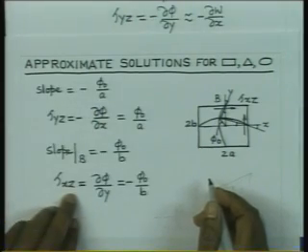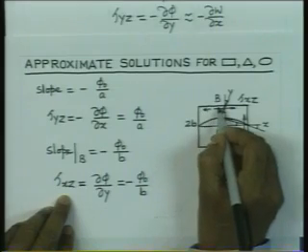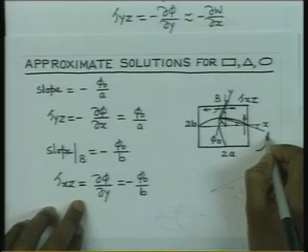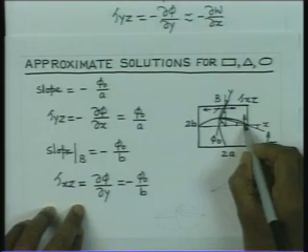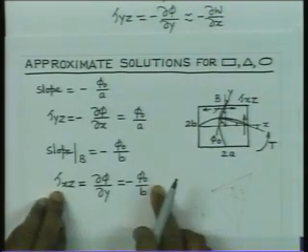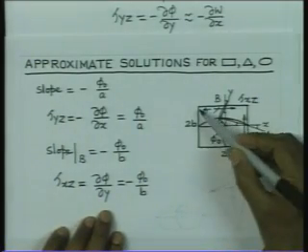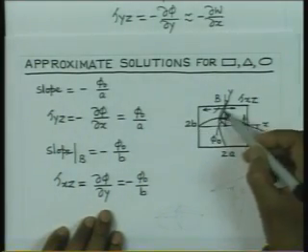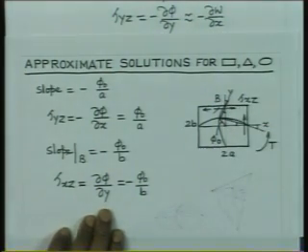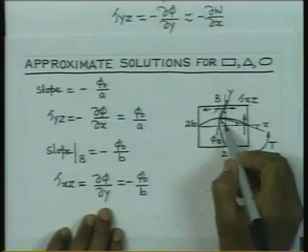What it means is that the stress cannot act in this direction, it is going to act in this direction only. So, that is not the direction which is correct, and if the torque on this shaft is acting like this, we know for sure that this stress here should be acting in that direction, and the stress here should be acting in this direction, and we have got the values correctly. So, herein without any difficulty you can understand that if b is less than a, we are going to get this slope to be higher than this one, and hence higher stress is going to act at this point, and the stress is going to vary linearly.